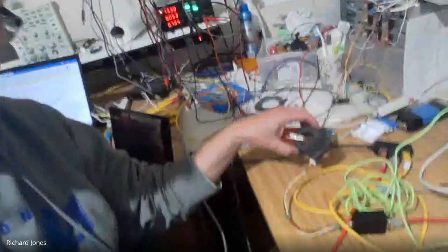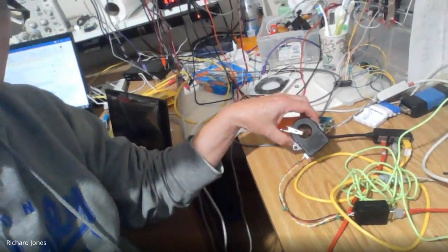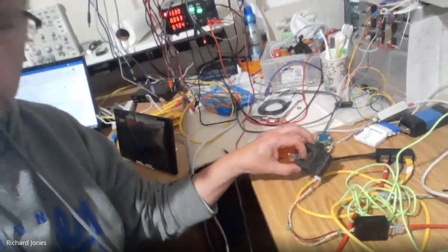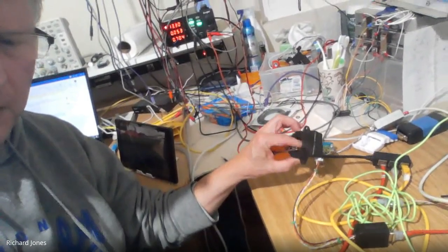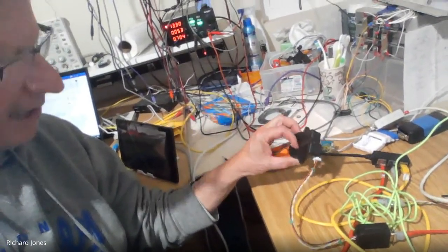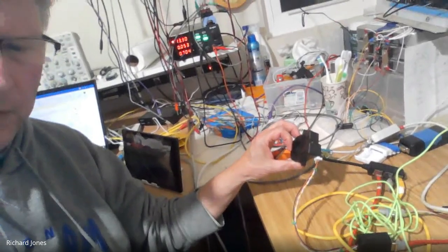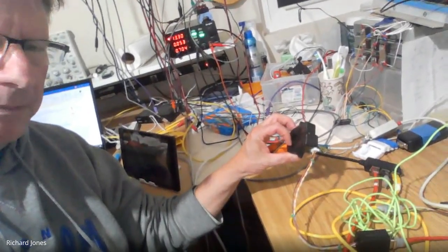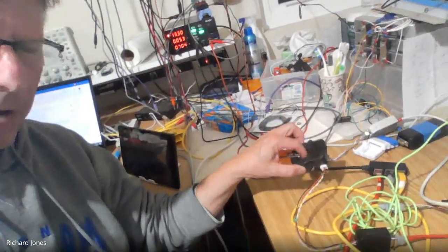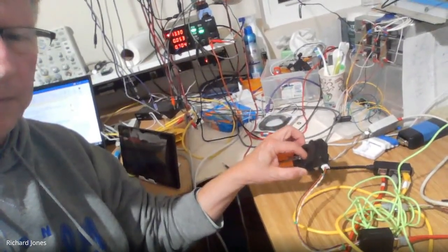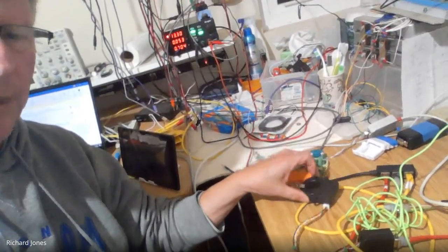What else do I have here? Another little sensor right here, which is commonly used. This is a LEM CAB 300. This is just a current sensor. It's a Hall effect current sensor. So you put your fat cable through there. I just have the old power supply cable going through here, but it can read milliamps. And this is a very cool tool if you want to do Coulomb counting and figure out how much current has gone in and out of your pack.